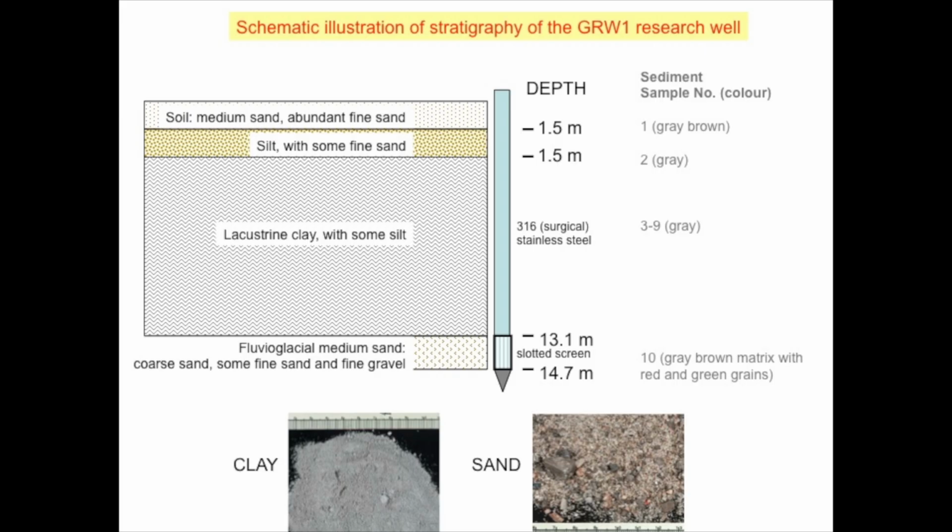This is a stratigraphy, so we're looking at about 13 meters of clay, which is old lake sediments, and here's our sand aquifer, and we're getting our water from here. So that's roughly what the clay and the sand look like. So this groundwater is protected by 13 meters of clay.